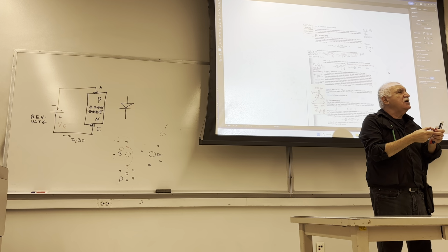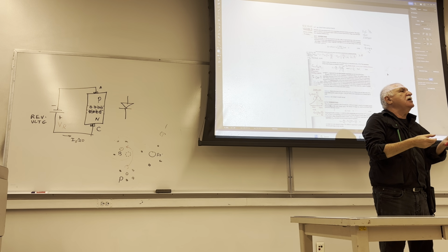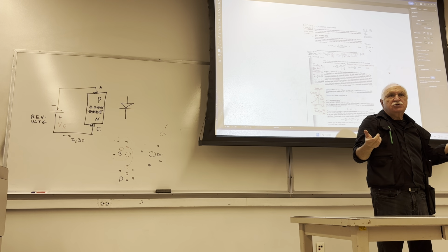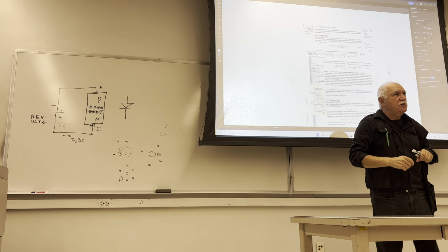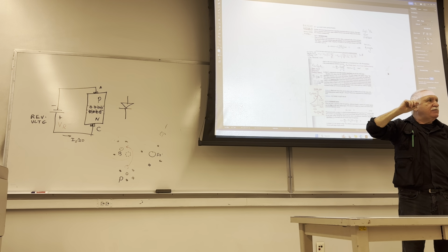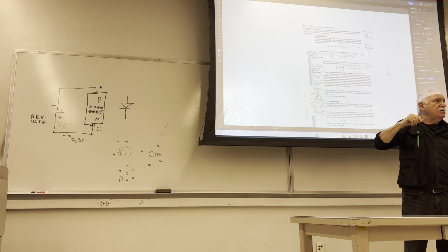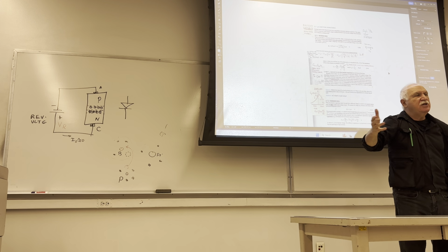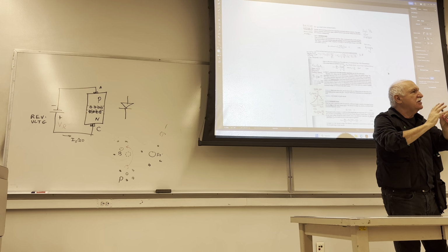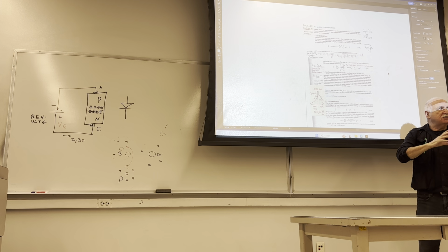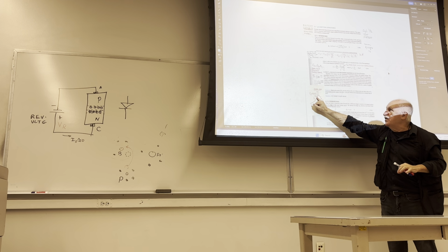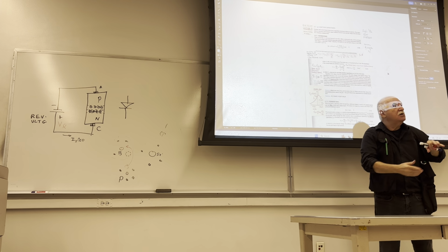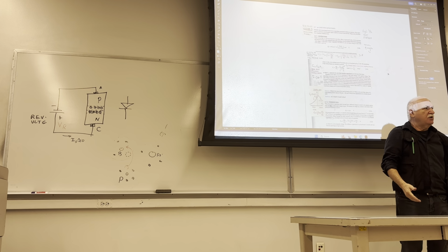In other words, if you take a diode, indeed, it acts like a capacitance for a small signal. Literally, it is a capacitor. You apply, for example, 1 millivolt peak-to-peak sinusoidal, and you will see that the current will be shifted by 90 degrees, just exhibiting the impedance of a capacitor. And the value of the capacitance will change with this profile. You apply a negative bias, and the capacitance will get smaller and smaller.